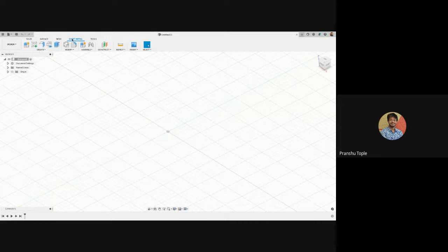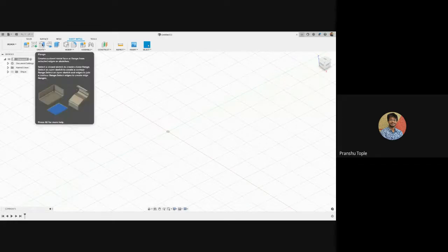So sheet metal is whenever you are working with metal sheets that need to be plasma cut, and once it is plasma cut you need to trim them down, then you need to, what we say, fold it. When folding, it's not exactly a 90-degree fold, it's a curved fold. So all this it takes care of. Here you can see it's flanging, so it takes care of that. You just need to make your model and it will automatically understand how much sheet of metal is needed.